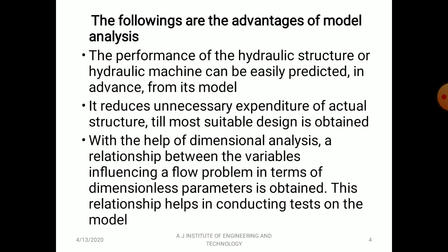With the help of dimensional analysis, a relationship between variables influencing a flow problem, in terms of dimensionless parameters, is obtained. This relationship helps in conducting tests on the model. I am going to discuss the Buckingham Pi theorem and Rayleigh method, which are dimensional analysis methods. By using them, you can establish a relationship between variables, for example density, dynamic viscosity, or length, diameter of the component.